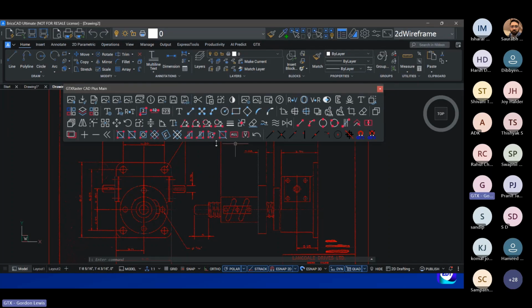We also do lots of different raster editing tools, like we can scale the image, we can set the coordinates for the image, so we can scale it to a specific line. We can offset, mirror. As you see, all of these icons here are very, very similar to what you see within the CAD. Rotate, mirror, move. So if people are looking at it, they can see exactly what the command is, and you get a tooltip that appears just to say what type of command it is that you want to do on the drawing.